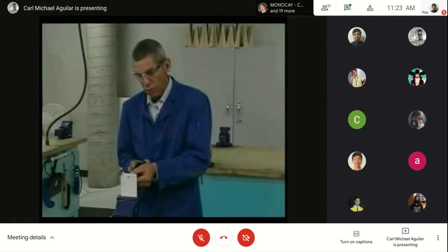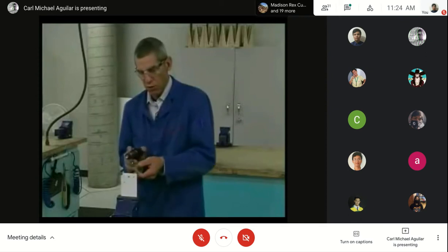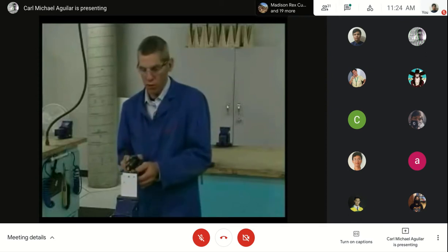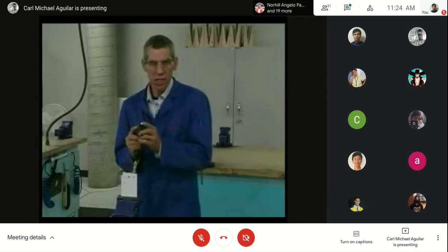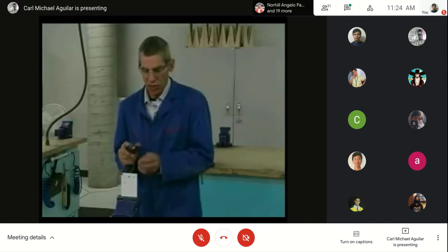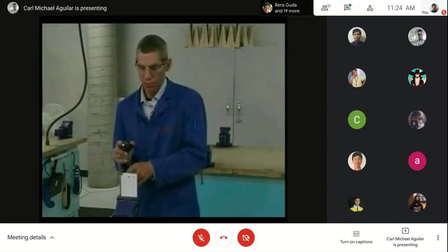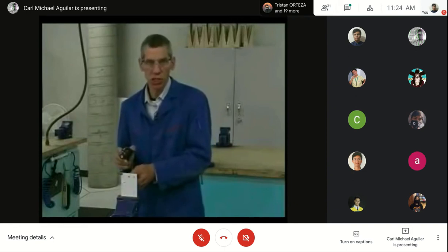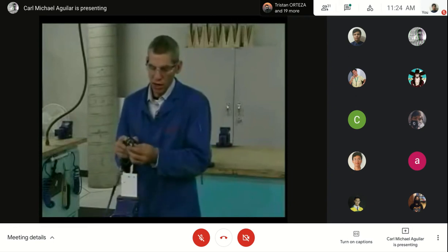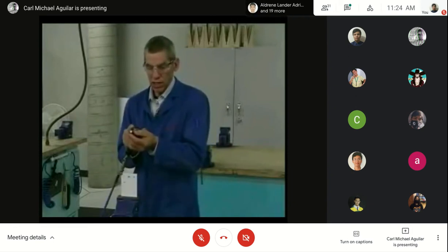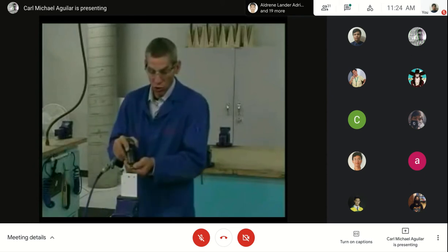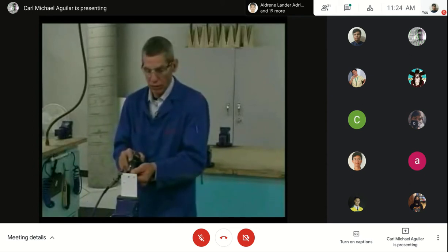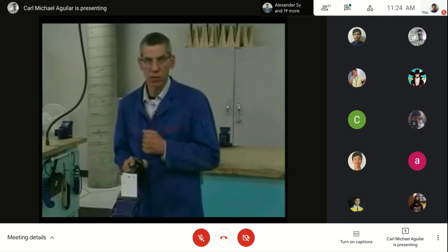By not having enough pressure on the manufactured head, the rivet snap can start to jump on the head and damage the head. If the rivet set is the wrong size, if it's undersized, it'll damage the head. If the rivet set is oversized, it'll damage the sheet by leaving a mark. If my rivet gun set is the correct size, but I'm not holding it perpendicular, I'm holding it off to one side, it'll damage the sheet.